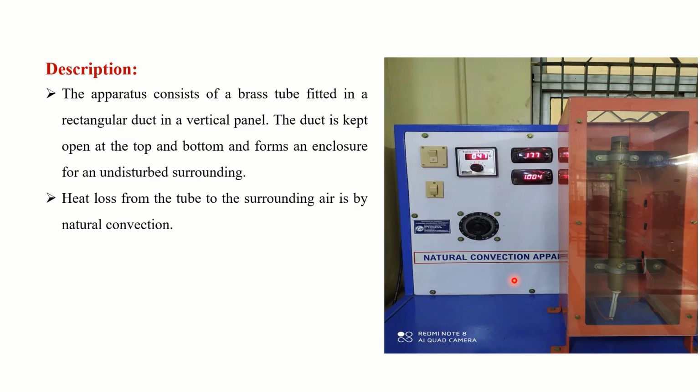When you switch on the main, from the heater, heat is transferred to the cylindrical pipe. Once the surface becomes hot, heat is transferred from the hot surface to ambient air. So it will get transferred to the air molecules adjacent to it. The air molecules will become lighter and move in the upward direction, allowing the denser molecules to enter into the duct. So heat is transferred to air molecules flowing across the cylindrical pipe.